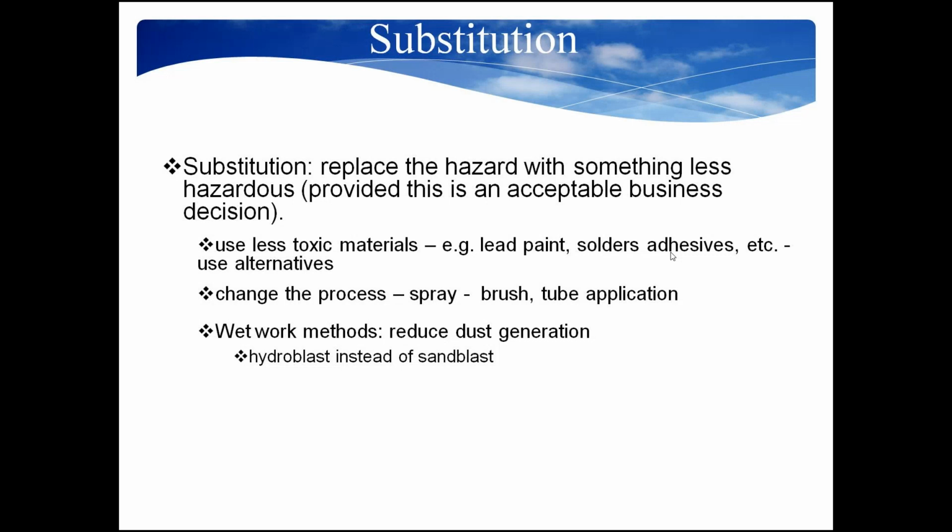You might change the process. Say you're spraying something, you might switch to brush or tube application, so it's less likely to become airborne. And then you might work with wet work methods to reduce dust generation. So you might hydroblast instead of sandblast.